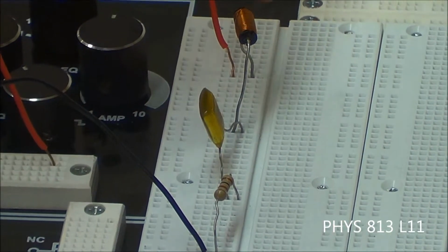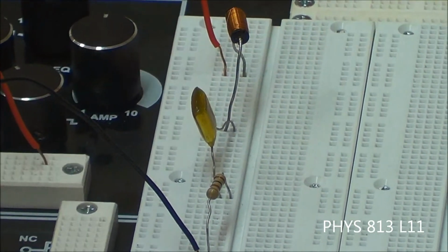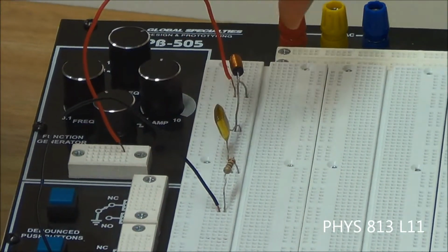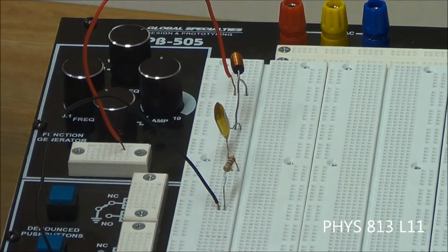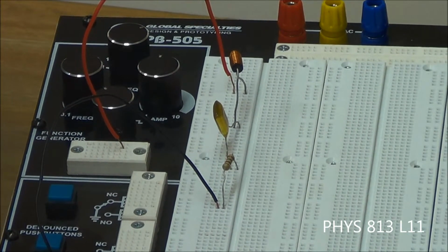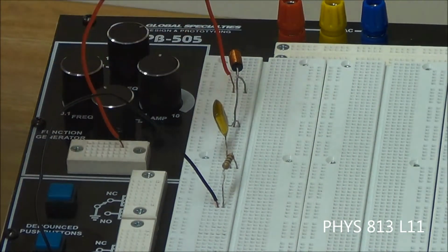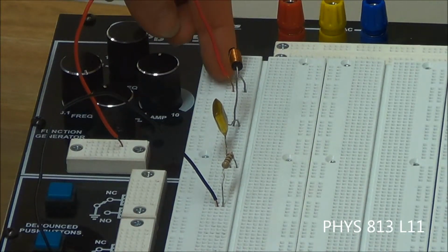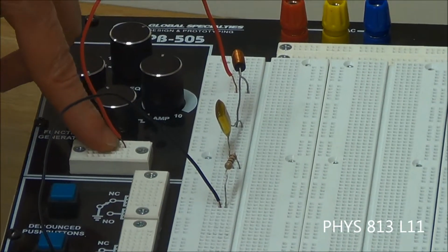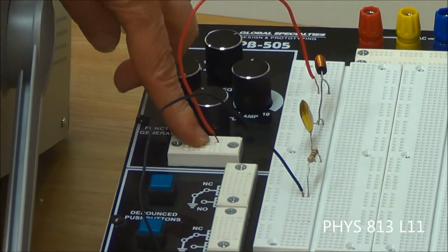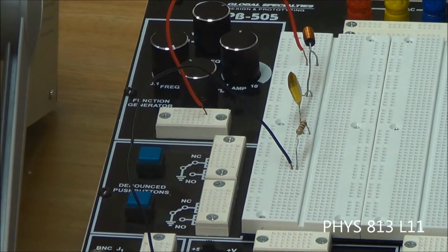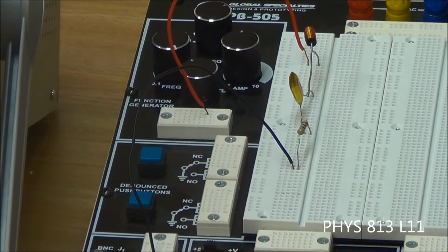Put the other end up here, and the little coil, you only have one of those, so you don't have to worry about that one. Put it in the same row as the capacitor. Remember that the wire from the coil is a little bit bigger than the others, so you have to be a little bit more careful about getting it into the holes of the circuit board. So then the other end goes up here, and then you have another wire from that end back to the position over here for the function generator. Now, I think it tells you in here where to set all of these things.